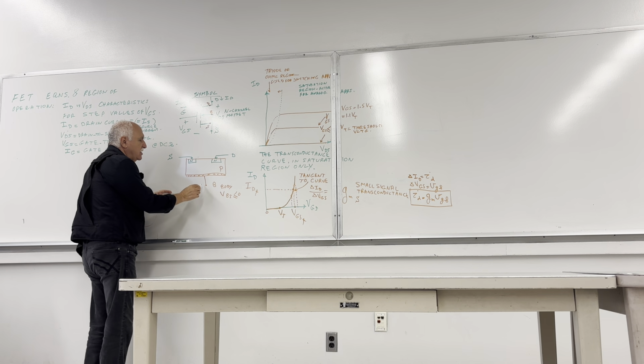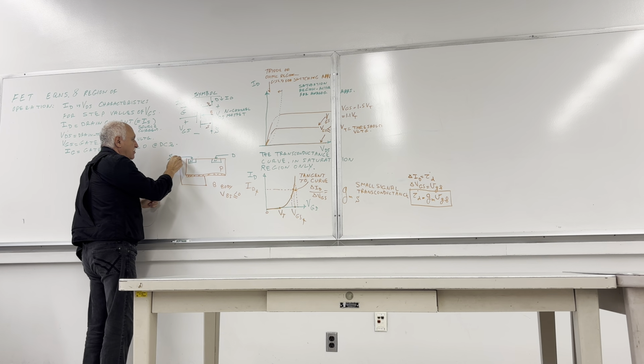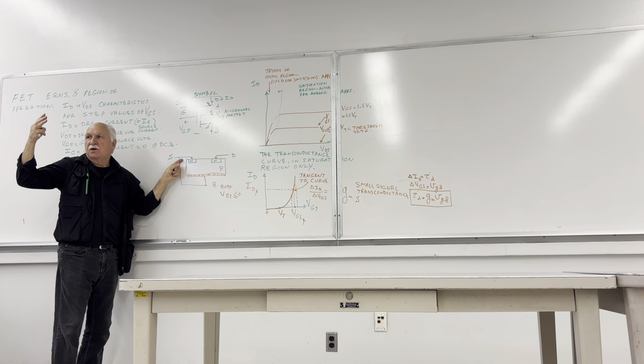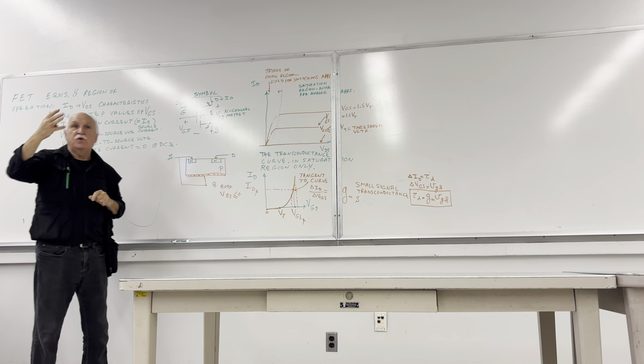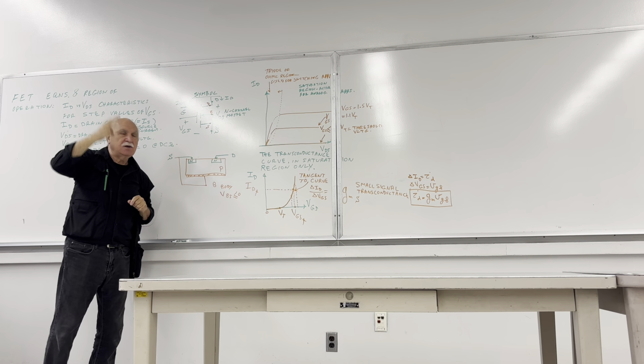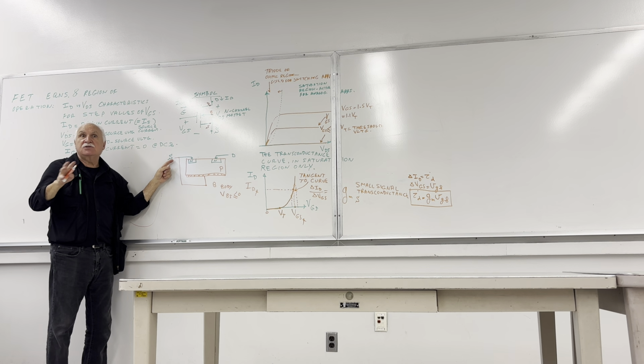We can usually connect them to the S, and therefore we can make a 3-terminal device. If you're getting a MOSFET that shows 3 pins, the manufacturer internally has connected the body into the source, and you cannot separate. It's inside the chip. But if you buy a MOSFET with 4 wires coming out of it, then the manufacturer hasn't done that.